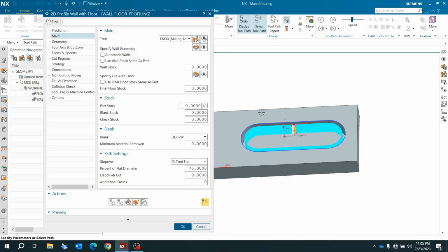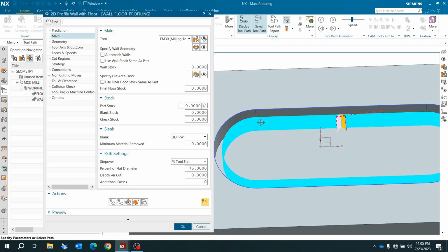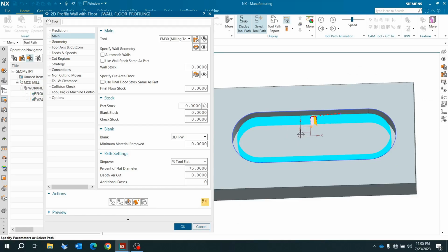Now sometimes there is more material available, for a casting or a forging part, if you are having 10 mm material to be machined, or you are having a pre-existing slot and after modification the size has been increased by 10 mm or so. Within a single stroke, you may not want to remove 10 mm of material; you may want 2 passes to be carried out.